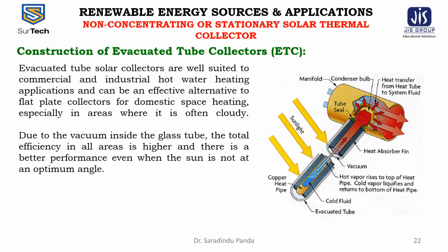For these types of solar hot water panels, the configuration of the vacuum tube is what is really important. There are a few different vacuum tube configurations: single wall tube, double wall tube, direct flow or heat pipe, and these differences can determine how the fluid is circulated around the solar hot water panel.